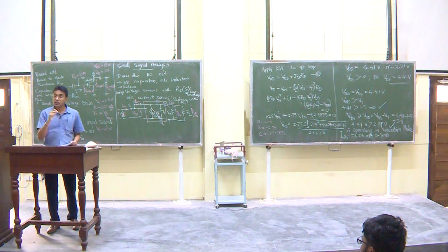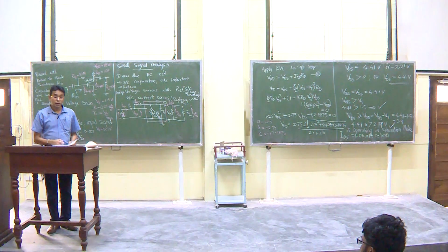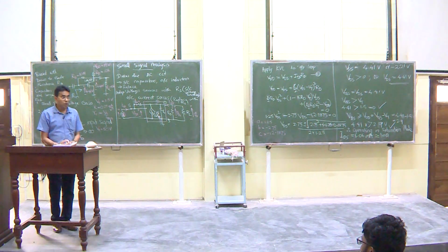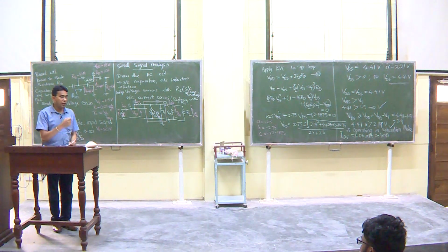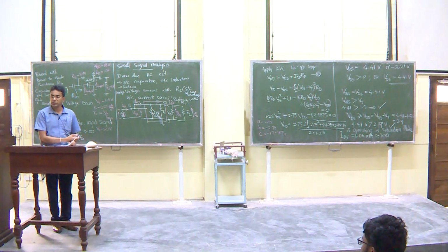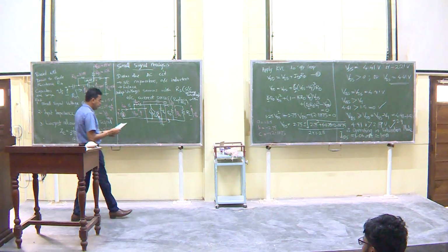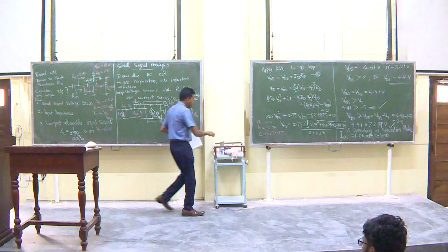So therefore, AC currents, the AC voltages, simple vgs and simple vds are not the same. There is a voltage difference, right? But the capital VDS and capital VGS, or the DC components, are the same. Okay? So we need to keep that in mind.